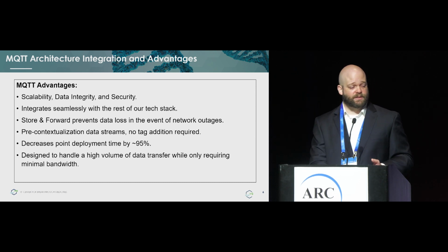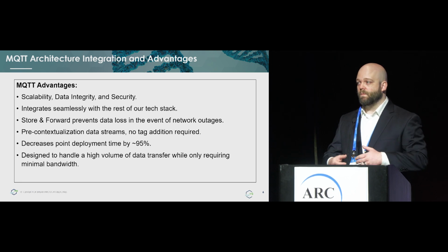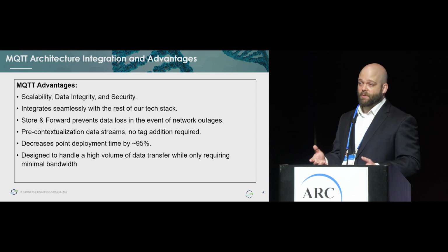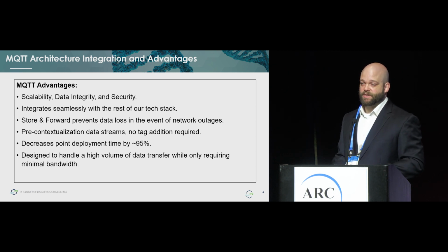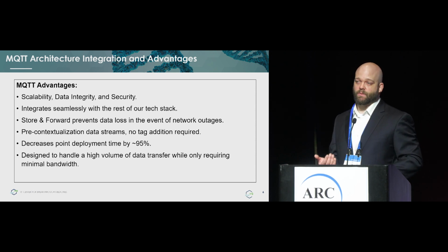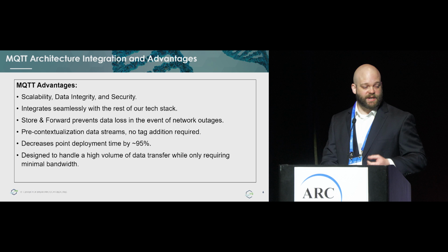One of the other major advantages of utilizing MQTT and Sparkplug-B is the store and forward capability. Recently, we did an update of our Canary system to a new version, which, by the way, took 10 minutes. I've never worked with a historian system you could update that effectively, that quickly. And as part of that, because of the store and forward capability, we had no data loss whatsoever. It just all backfilled after we were done doing the update, which was magnificent.